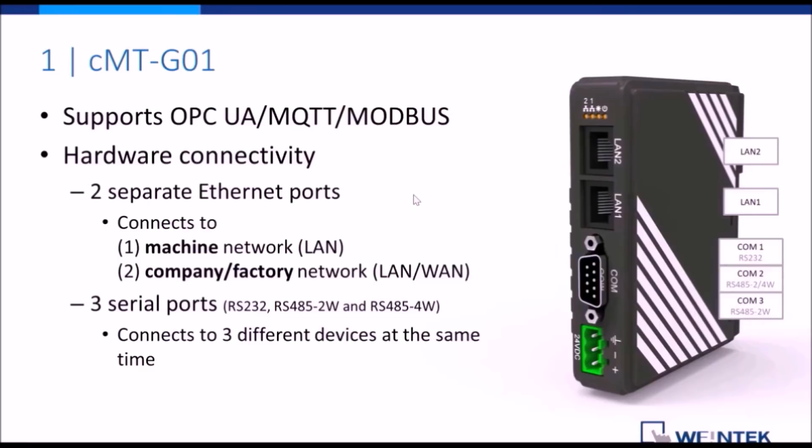And it has three serial ports within one DB sub 9 pin configuration, supporting at least one each of RS-232, RS-485 2 wires, and RS-485 4 wires. So you can have up to 3 different devices at the same time.